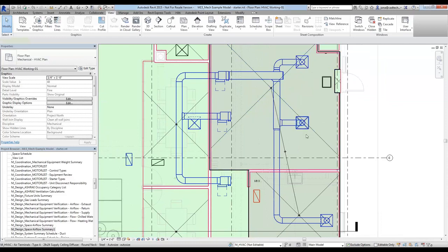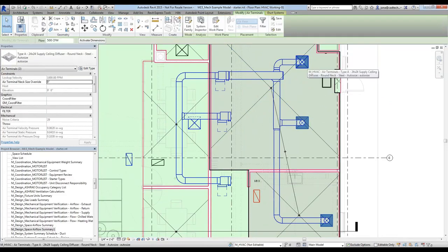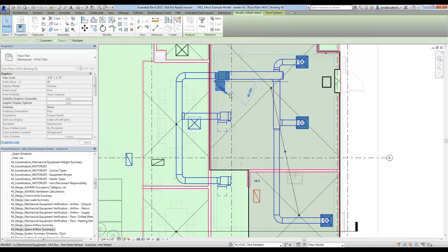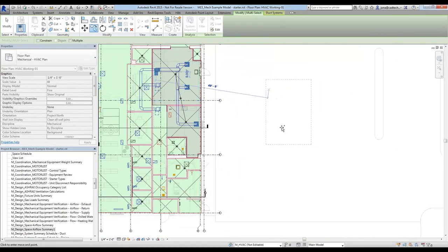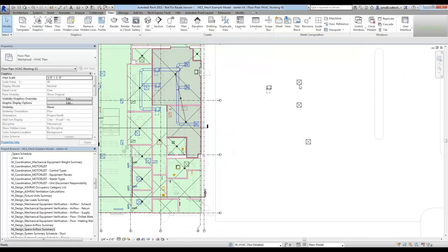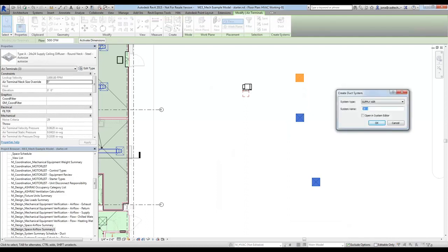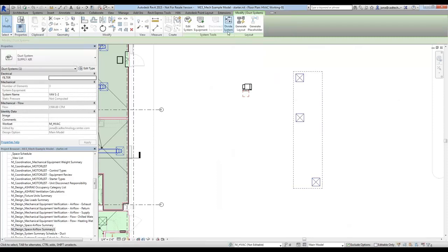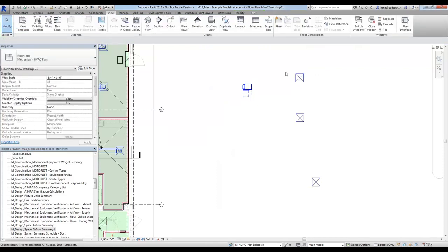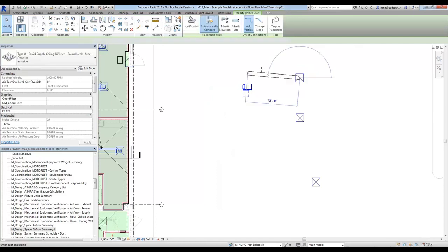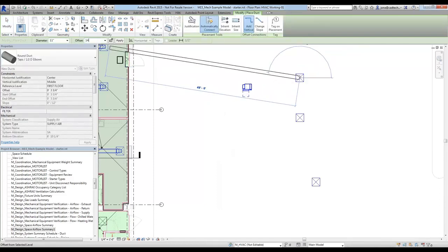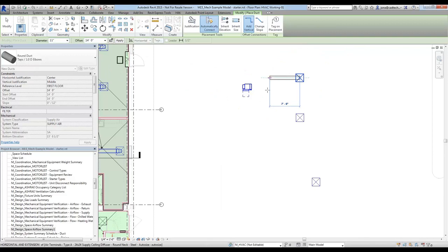Now, drawing ductwork from units, from this guy, I'm just going to set them out here in space for now. But we can come in here, quickly hit ductwork, call him VAV 1-2, select our equipment. And we could come in and manually draw everything, call it 14 feet, draw one there, and come all the way down to here.